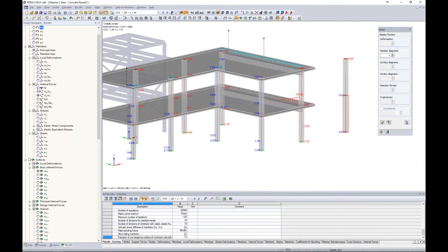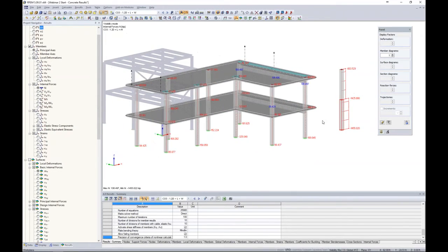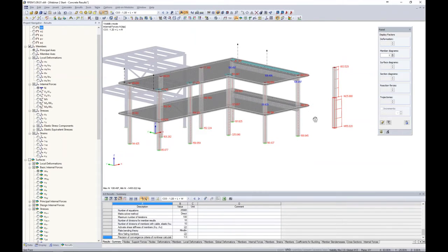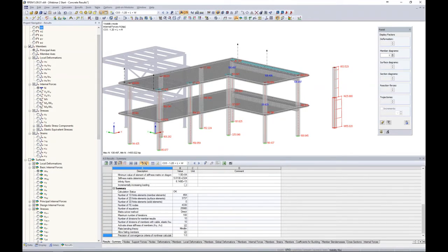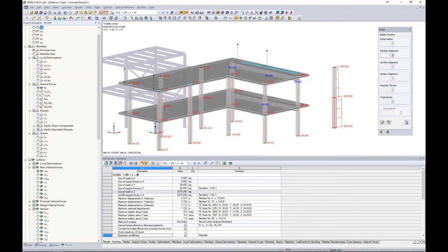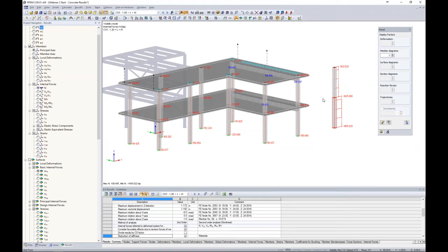Now lastly, we can even take a look at our axial loads. So why would our axial loads be important? Well, if we're interested in the sum of our forces, I can see that for my concrete structure only, the sum of my forces in the Z direction is 1,455 kips. Now this is different from the table down here shown in my results summary, which also gives you the sum of the loads in the Z direction, but that is for the entire structure, including the steel structure over here. So again, the result beam would be beneficial for only part of your structure.